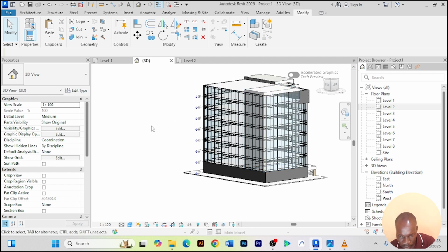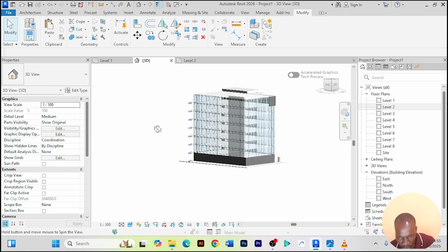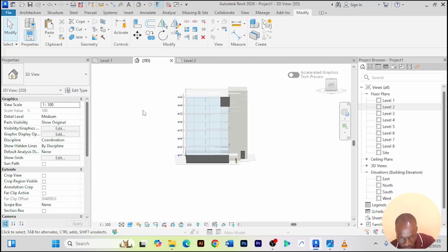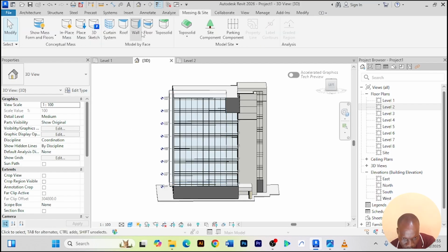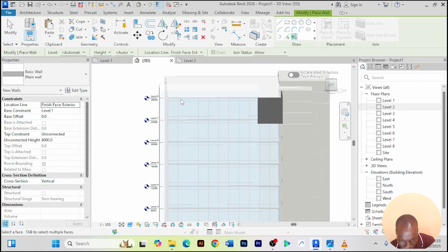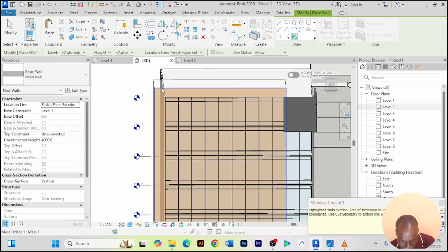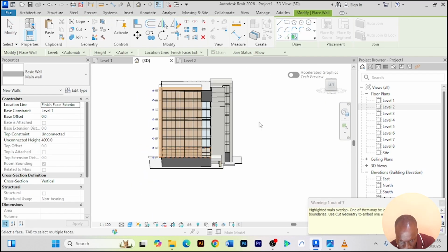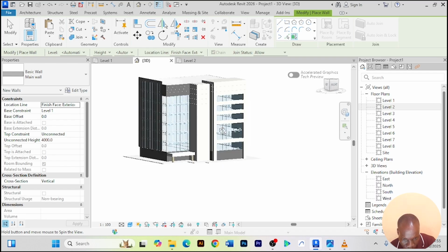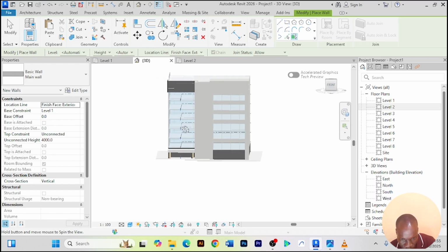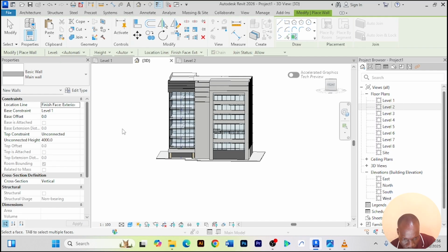You see it is here, though it has no color. Now we can turn it into wall. So you'll simply come to mass and insert, you select wall. Now you can simply place the wall. Let me see what they have. Okay, they are complaining because this wall is closed, it is attached to the other.